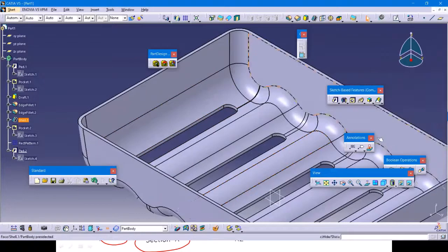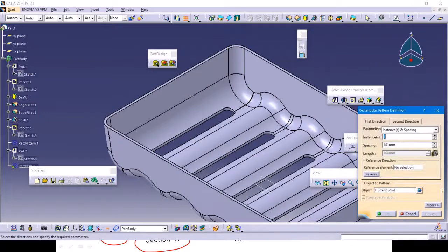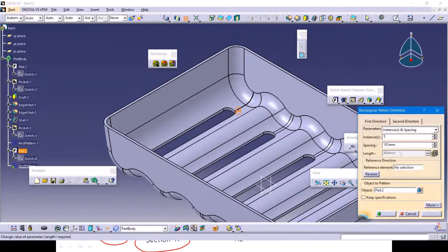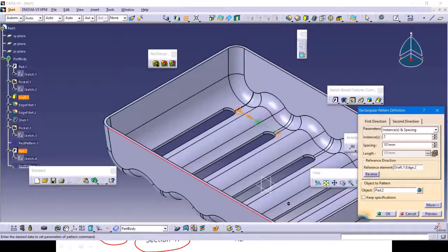Let us see in front view how it's going to look. Now it has not met exactly with the bottom surface. Let us edit that pad option. Go for mirror extend, more. I'll remove that. Now on one side you get an 8 mm dimension downside, on the other side I'll go for up to next. Let us see how it has been merged here.